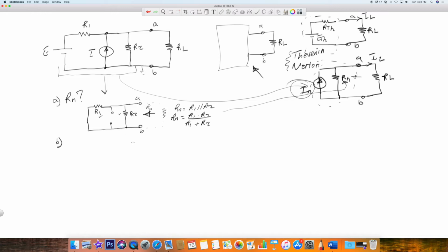Here's the major difference, however, so I need you to pay attention to this. Whatever we do, we're going to short out A and B. Let me repeat: we're going to be shorting A and B, and we want to measure the current as it goes through A and B. So first, we're going to put our voltage source right here.